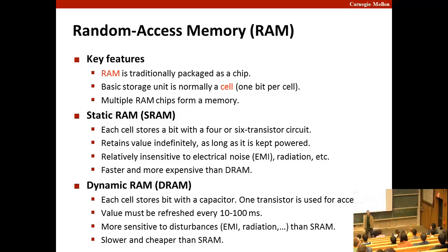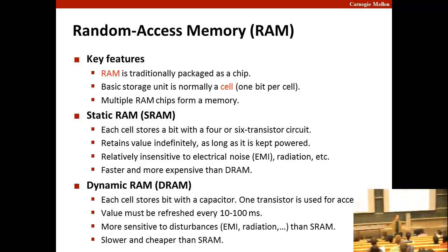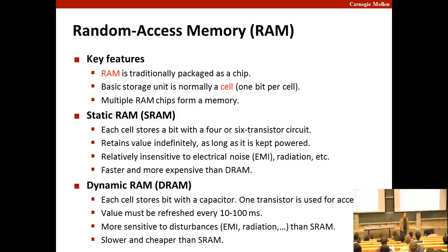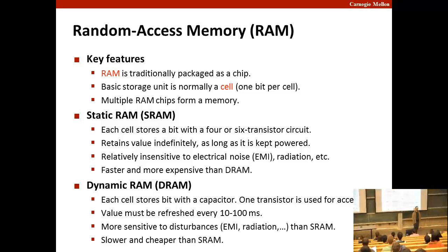The memory controller reads the value, compares it to some level, and then if it's above the threshold, then it reads it as a 1. If it's below the threshold, then it reads it as a 0. Right. So we certainly can imagine that it walks linearly through memory and does a refresh by reading and rewriting. I just don't know that that's actually what it does. Maybe you do, but I think it's actually more involved than that. Because DRAM is a collection of cells, and there's a buffer to access it, and I don't think it actually pollutes the row buffer when it does the refresh.